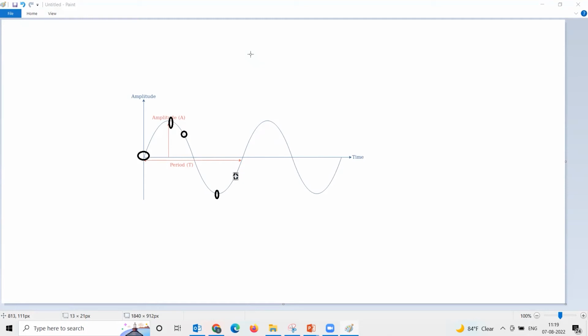You may not have entered the proper parameters. That means it's a modeling error which you need to check. But literally what I'm trying to say is, when your short circuit current which is identified in ETAP is higher than the actual fault current, your simulation is right. And we are trying to find out the short circuit study, the worst case, just to select the switchgear rating, bus bar rating, cable rating, etc.